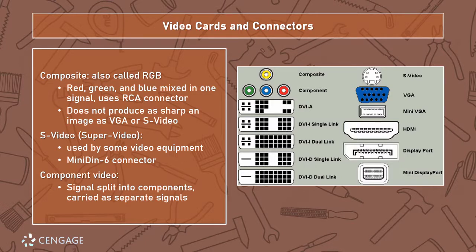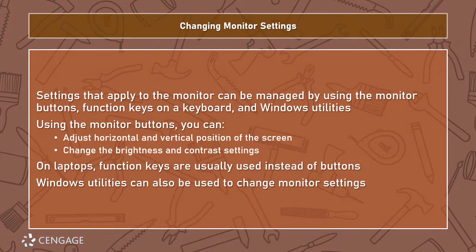But as you can see, there's 5 different versions of DVI. So it's always important to understand which one you're trying to use for your particular connector. Make sure you don't accidentally bend up the pins or try and connect a cable to something that doesn't belong to. Now, once the monitor is connected, there's a ton of customization we can do.